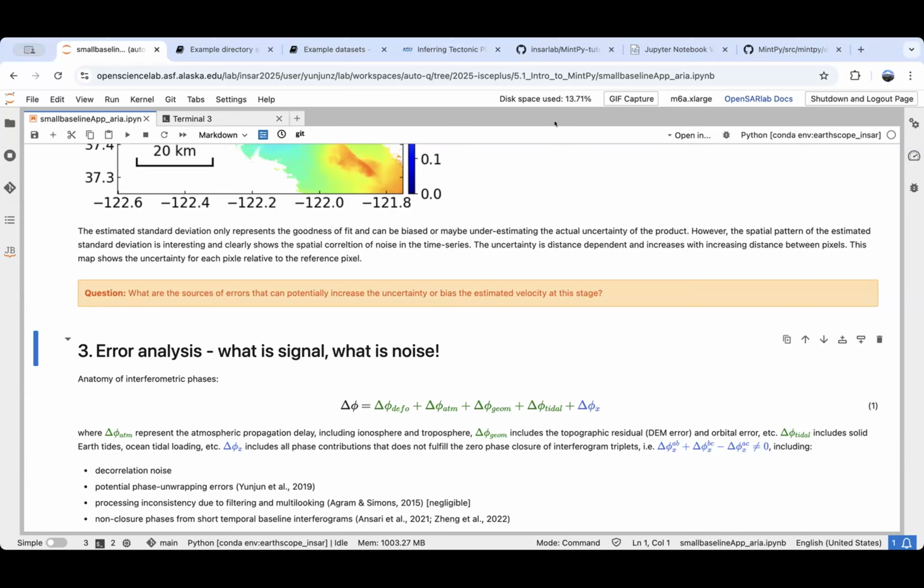If you base your analysis on spatially filtered interferograms, the standard interferogram approach that we've discussed so far, then you need to require short temporal baselines, because now you're relying on distributed targets and they decorrelate with time rather rapidly. So if you would form interferograms with a single reference, most of your interferograms will be decorrelated and your solution will fall apart.